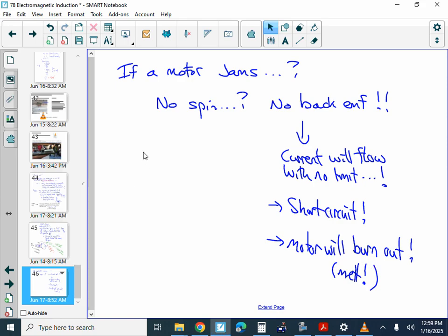Okay, so a while ago, I heard the blender in the kitchen. My wife was blending a cake or whatever, and the cake batter was really thick, and so the blender was struggling, like the motor was barely turning. So I came rushing over to stop the blender from burning out. I basically said, you've got to have the setting a little higher, or have the beaters not as far into the batter or whatever, make it so that the motor can spin. By the time I got there, there was some good electrical burning smell going on. The blender still works to this day, but it definitely wasn't good for it. It was starting to get really hot.